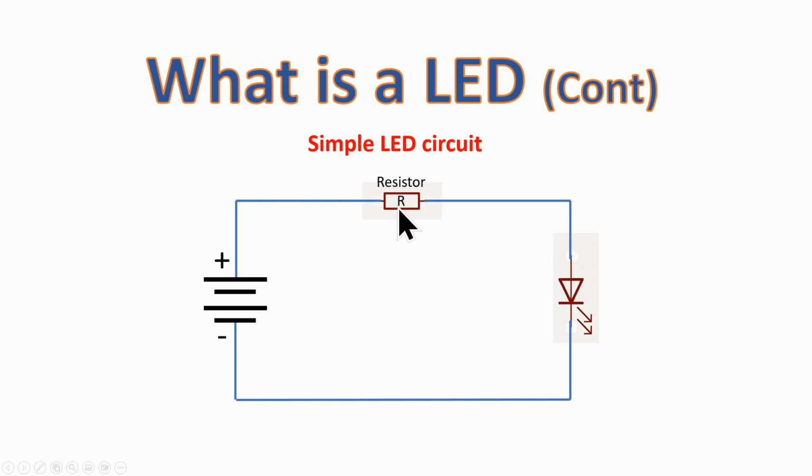So at our level, I would say, let's just always put this in. If you keep this voltage below the forward bias voltage of the LED, it is possible to run it without that, but these are so sensitive and change with temperature and from LED to LED that it's best to put this in and limit the current going through it.